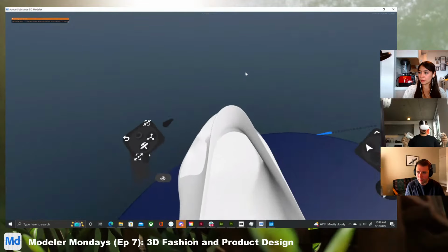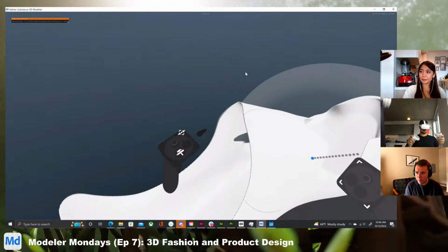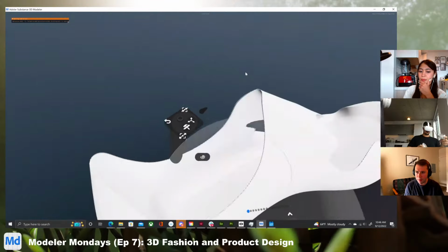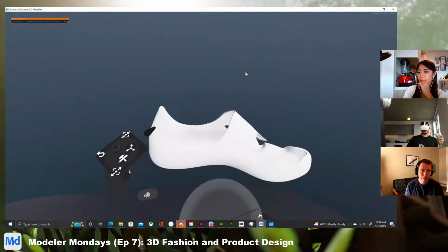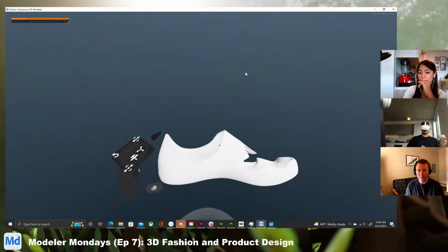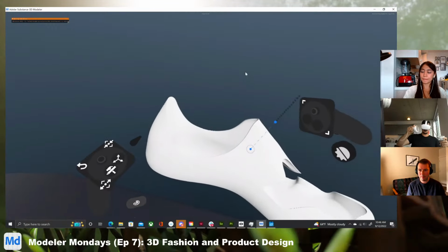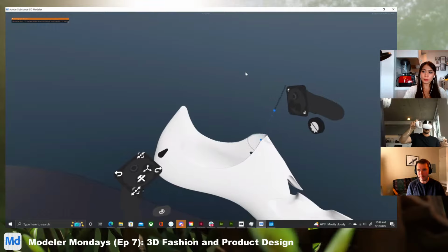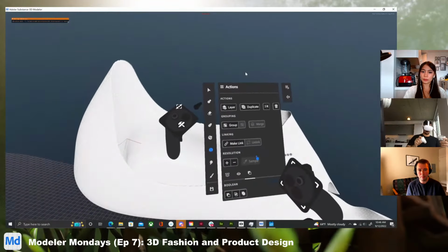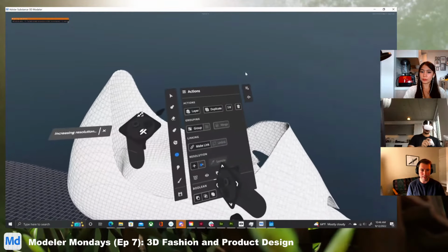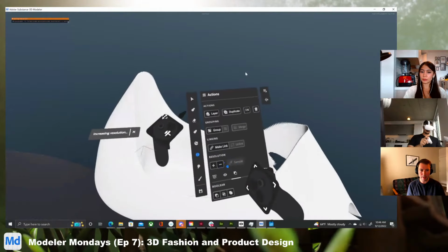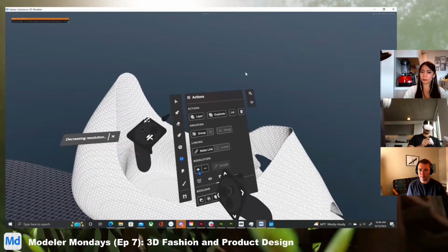I've got a question from Fry Pixels. He asks, would you create a secondary group to keep the original since it clears the bool objects? It really is a case-by-case thing. If you only needed to make that central shape, then yeah, you can just clear it and have that remaining. But if you wanted to make multiple parts, like Nick might want to do for his project, then saving an original is a good idea.